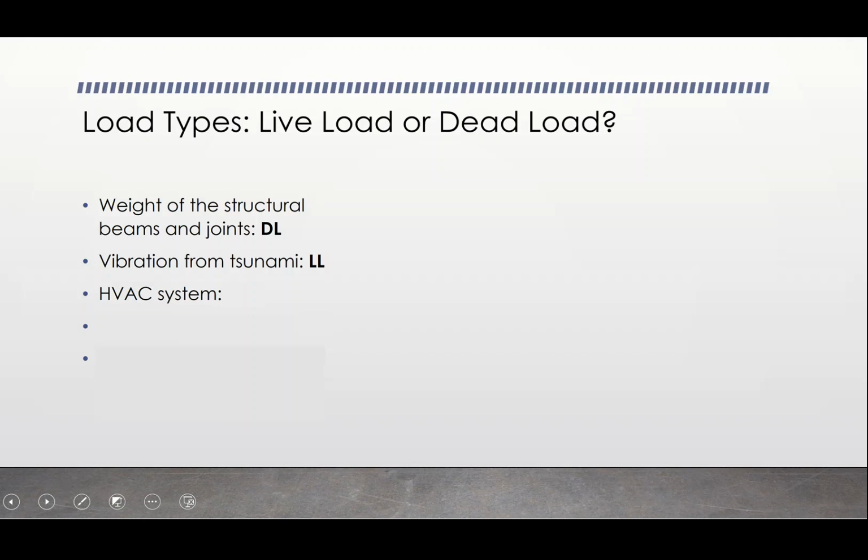Okay, HVAC system. That one's a little bit harder, when we think of furniture and things being able to move in and out, moving boxes, things like that. The HVAC system doesn't really fall into that category. It is made up with the building, and it's usually designed around. So that one would be considered a dead load.